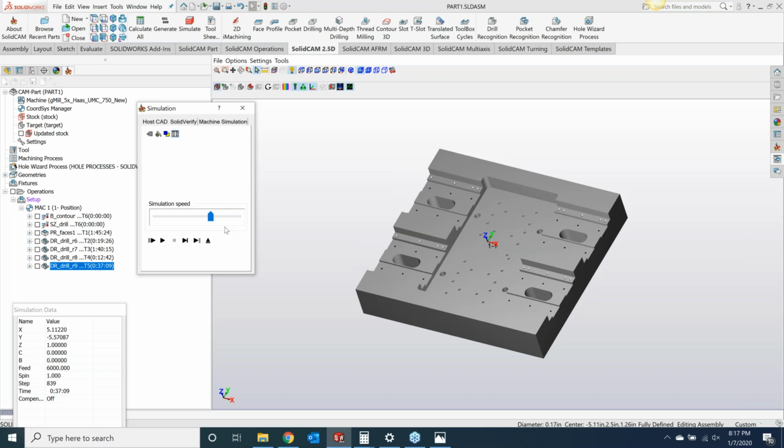Yeah, that's a great point. So what we could do in that chamfer section is just limit it to anything that is 1/2 inch or smaller, as well as filtering out so that when I switch it over to manual, we could manually grab those four 5/8 holes and use a larger spot drill at that point, or not use a spot drill at all, whatever you guys are looking for. Is that where you're going with that, Greg? Yes, it was. Okay. All right.